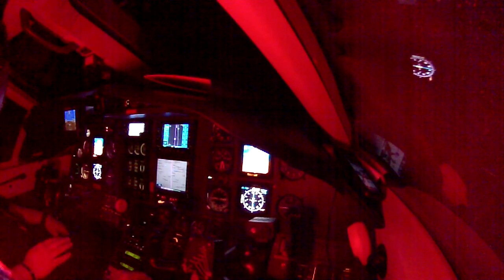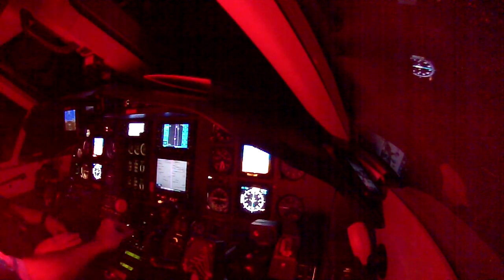Okay, now we're on heading mode. And you can go ahead and select right there on the button on your left side. Go ahead and push. Basically, if you push AHRS 1 over there, you select AHRS 2, and it's going to give you attitude 2 and heading 2. You're using the other side.